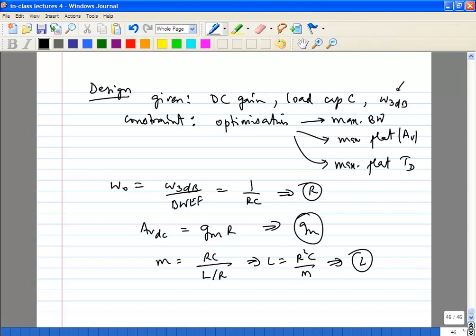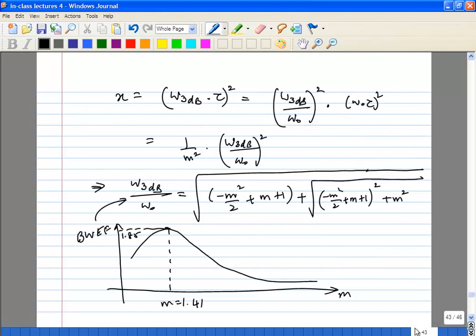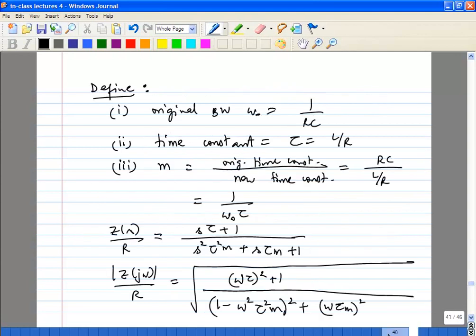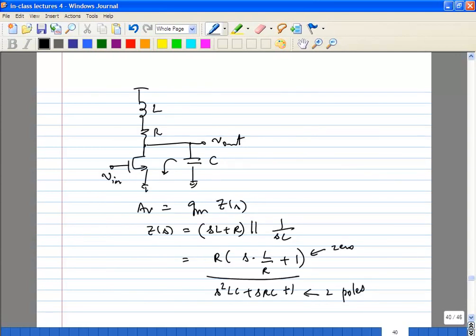Now the other thing to remember is, if you go back to your amplifier, unlike your narrowband wireless RF circuits, in this case you actually have an explicit resistance in series with the inductance. In other words, you don't care much about the Q of the inductor. You want the inductance, but you don't care about Q, because the resistance will probably be in hundreds of ohms.